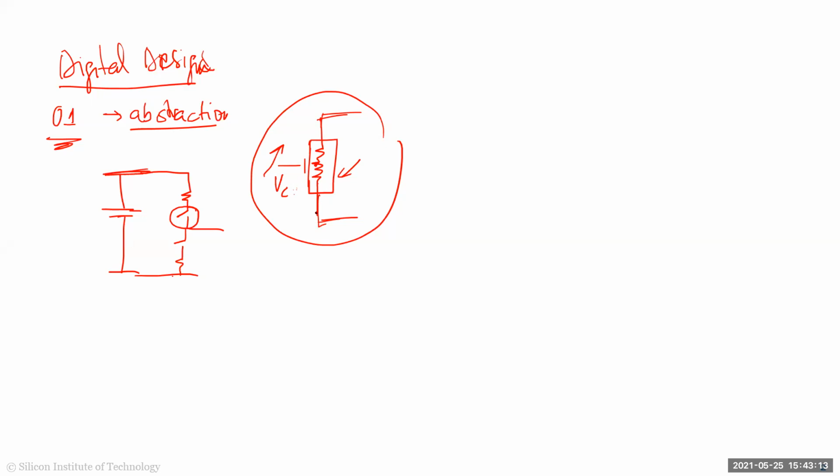So what we're going to do is look at the metal oxide semiconductor sandwich, and see what decides this control voltage, this threshold voltage, at which the device becomes conductive or non-conductive. But before we look at the complete device, we'll just take the capacitive structure, the MOS, oxide and semiconductor, and derive the equation of how to turn on and off the channel, or turn on and off the resistor, basically. Okay.